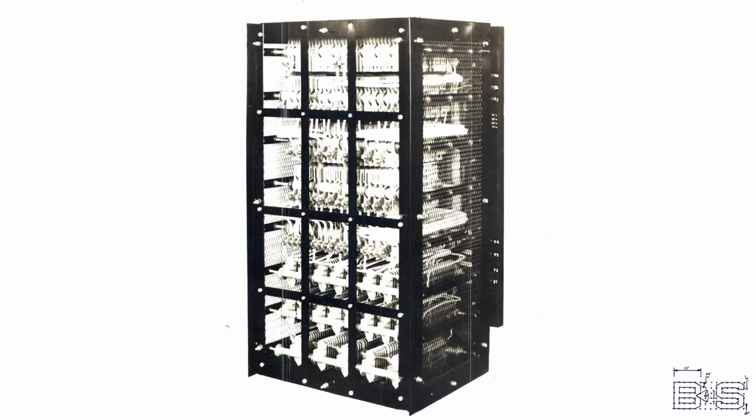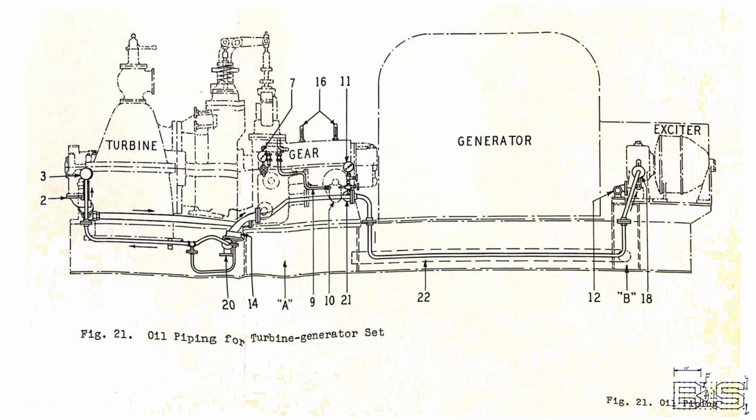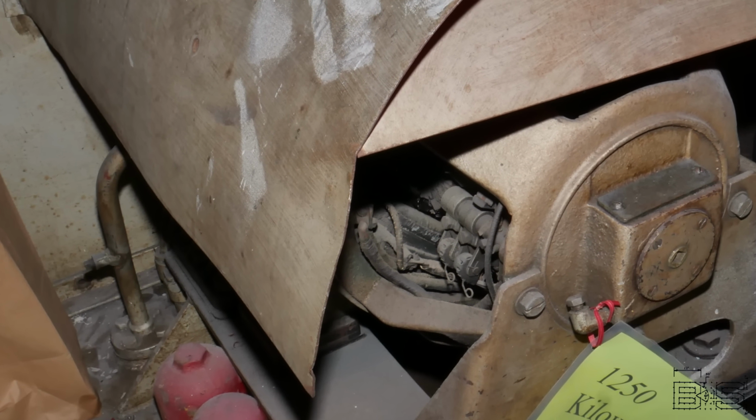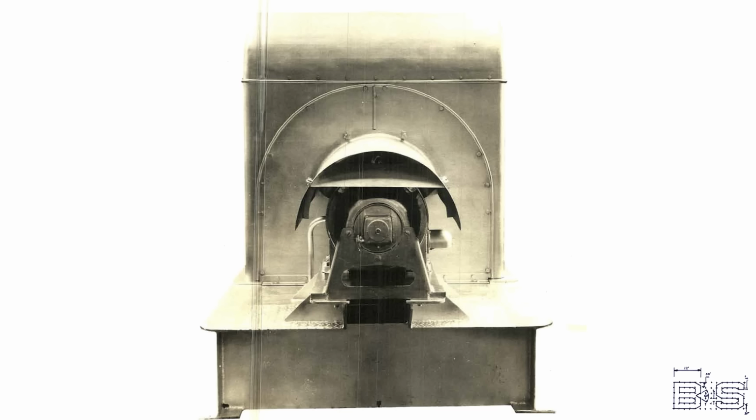The rotor creates a magnetic field with 10 field coils that are supplied by 120 volts DC. However, this can be adjusted by the field rheostat. The rheostat consists of a series of resistors that are cut in or out by a moving arm. The actual rotor current is generated from the last piece of the turbo generator, the DC exciter. It's a compound wound generator rated at 10.5 kilowatts. It's of completely open drip-proof design. The generators have a shield over top to keep dirt from falling in.